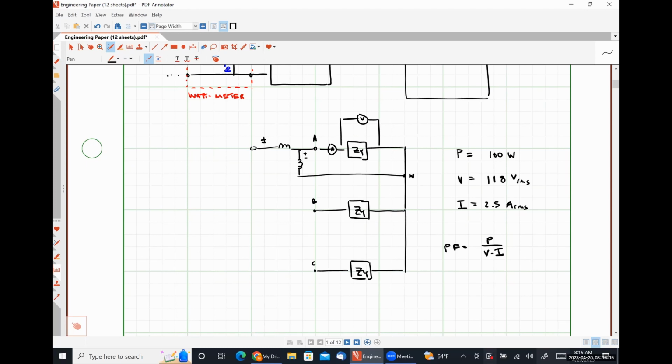So if it were a motor, the angle would probably be positive because the overwhelming majority of motors that we're going to see are induction motors and things like that. But we have enough tools here with a multimeter and a wattmeter to figure out a lot of different physical characteristics of the power that's being absorbed by a practical machine.